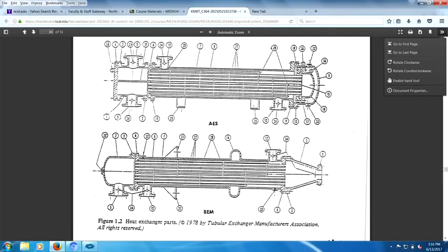The second hold point is you have a tube sheet sitting here. There's a tube, and it's a sheet of tubes. You want to watch how the tubes are inserted into the tube sheet. There is no pounding with a hammer. The tube opening should be free of burrs and there should be no lubricant used.